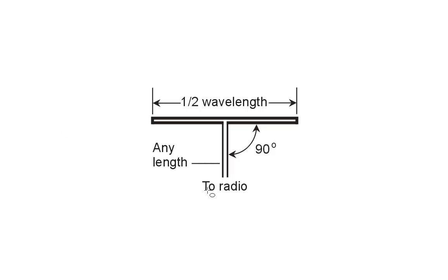Generally speaking, we'd need an antenna tuner for an antenna like this if we wanted to use it with ham radio equipment, because this will have about a 300 ohm purely resistive impedance here. If we run 300 ohm transmission line here, we would need a 6-to-1 impedance transformation to get the 50 ohm pure resistance that the radio would want.